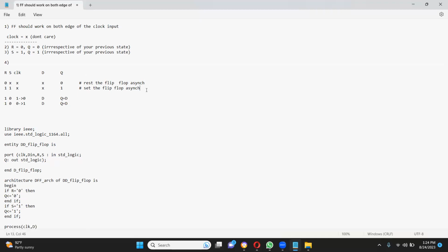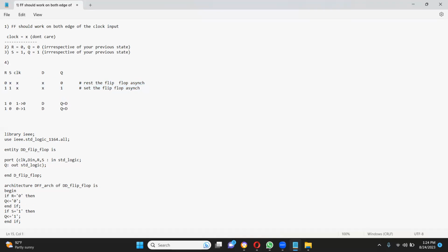Set and reset is needed for these 2 cases. It's only needed for the first 2 cases. Yes, you are right. Set and reset is irrelevant for these cases, but relevant for the other 4 cases. You can simplify it to 2 cases. I mean, Q equal to D. It doesn't matter whether D equal to 0 or not. Q equal to D. Simple.